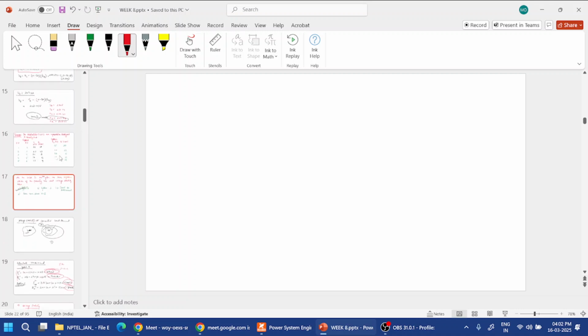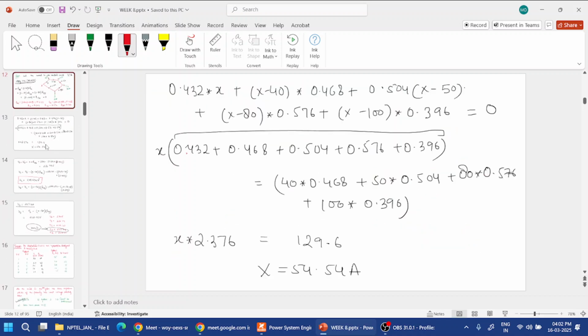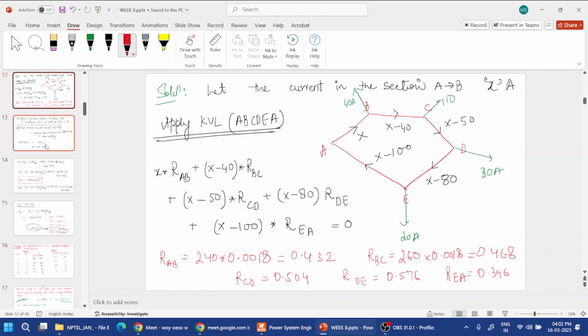See, what happens here? We just solved the question just before. Here, what we saw is that at the source, when the supply is given at A, in the consecutive nodes voltage gets dropped, and you can see here at D we have the minimum voltage. But at E, the voltage gets increased.